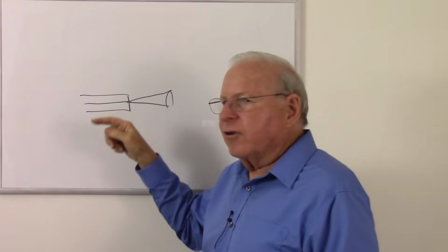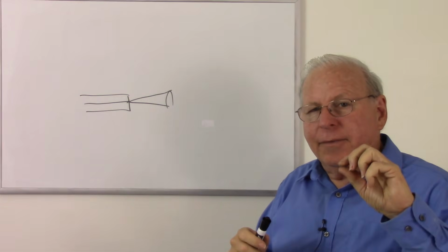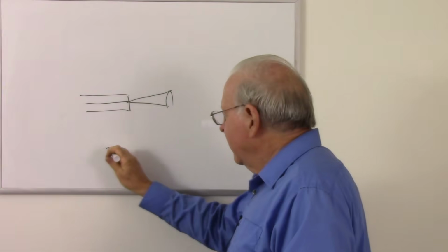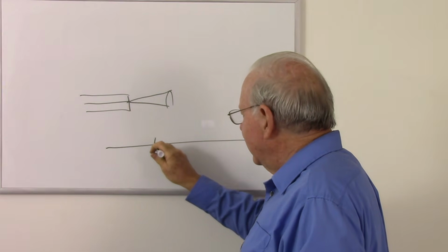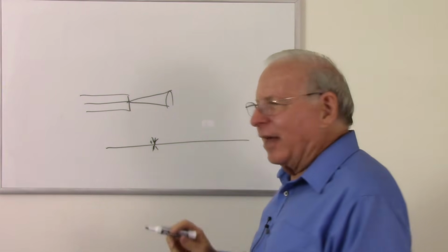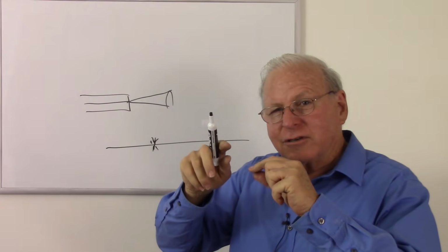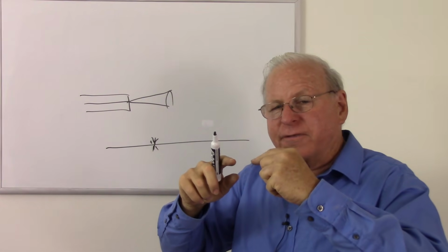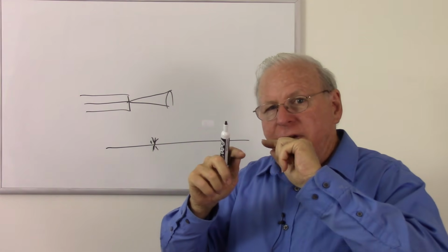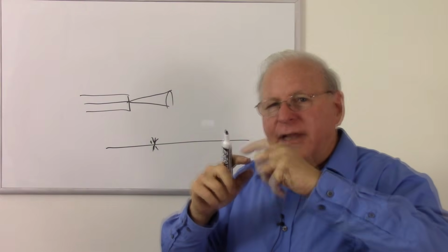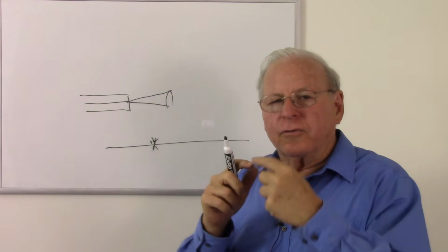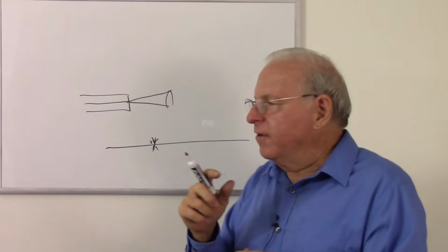You get that red laser going through there, and if there's any break in the fiber, you look along the fiber and there's a bunch of light leaking out right here. That's where your break is. And you can also, just to show that it happens, wrap that fiber around your finger and it'll light up because you're getting too small of a turn, and the light now no longer goes through at the critical angle and starts to escape from the fiber.